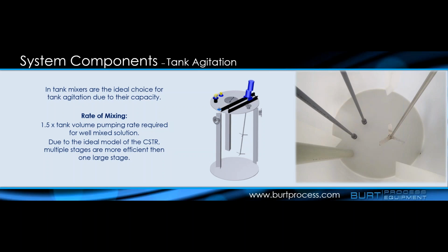On very small tanks, people do use recirculation pumps for agitation. It's not as common on bigger tanks or bigger systems as a mixing means, and that's because, as I just said, you need a really substantial pump and a lot of power and horsepower to really get that agitation going. Instead, on larger systems, recirculation pumps are utilized more as a carrier medium to allow for easier reagent injection.